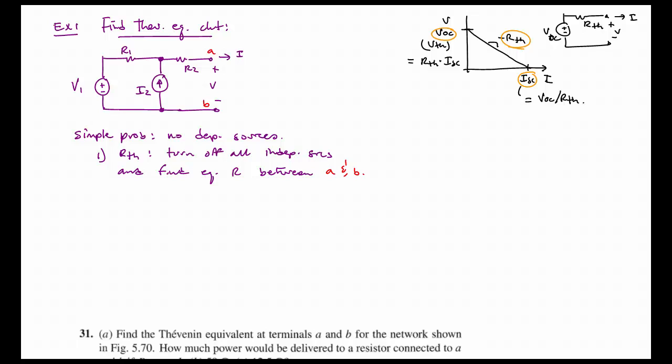Now think about it. If we have this Thevenin equivalent network up here, and you turn off the independent voltage source, V open circuit or V Thevenin, which is due to the net action of all of the independent sources in the original network, you see that all you're left with is R Thevenin. So when you look in, you see just R Thevenin. Well, you do the same thing to the original network: turn all the independent sources off.